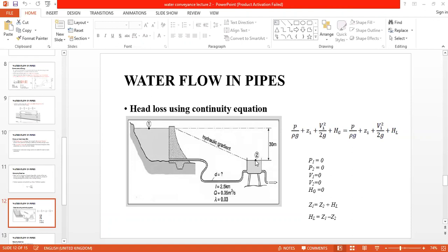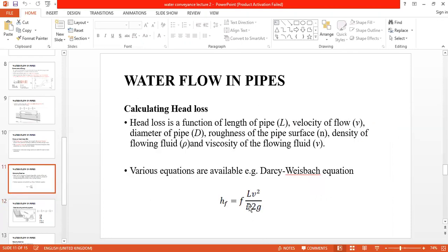We're going to use this as well to determine the diameter of our pipe. We have two things which we need to know: the diameter of the pipe to use, and how much energy is being lost in that pipe. If you look at the equation in the previous slide, as we reduce the diameter, the head loss is increasing. Of course, if we reduce the diameter, we increase the rate at which the water is coming to our farm.